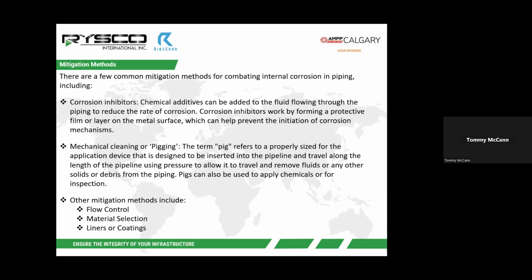Most common, in my experience, and not in every market, but generally speaking, would be your inhibitors. So where you add chemical into the system to try and reduce the corrosion rate. There's many different types of corrosion inhibitors using different reactions and bases of their chemistry to work, and they usually have to be fairly fine-tuned to the individual system itself, because you're trying to affect that chemistry.